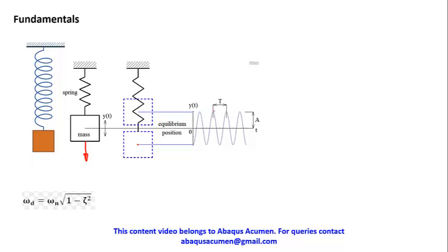And then for your frequency, if you take two peaks, or take this time interval, and then this time interval, and take one by that time, that is nothing but the natural frequency of the system. So if you take any system and disturb it, it will start vibrating in its natural mode. This is only 1 degree of freedom, so you are seeing only one mode shape, up and down. This is just an axial mode you are taking because it's 1 degree of freedom.